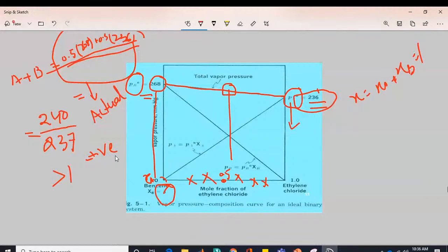Okay, so this is an equipment where you can see your feed is pumped into a heater where you're going to heat up that feed, and then you have this pressure reducing valve, and when you lower the pressure, when this comes here, what happens is this gets a cooling effect. You already know that when you go from higher pressure to lower pressure, the effect of cooling is activated.